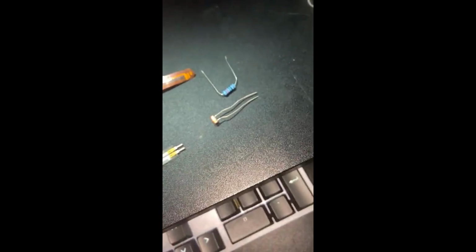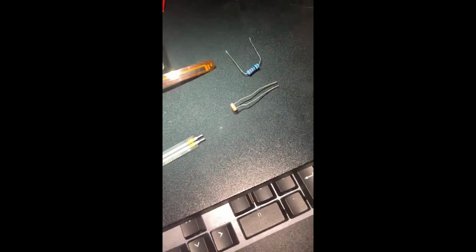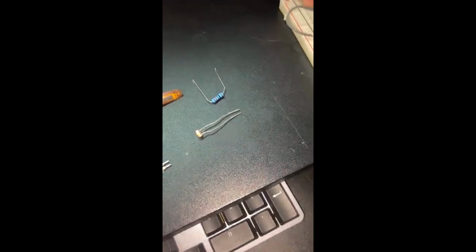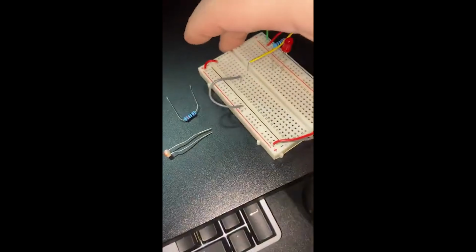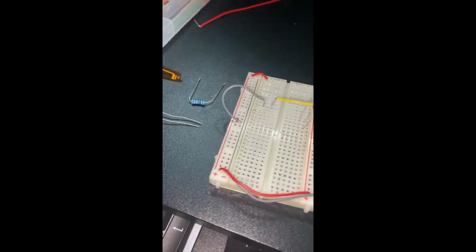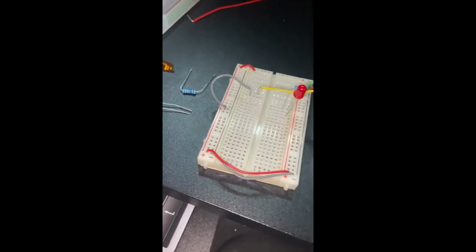So I am going to get another resistor right here. This is a 10K ohm resistor, the same one actually we used in the previous video with the button. And I'm going to set up this voltage divider. Because again, this doesn't have that built-in resistor of the potentiometer, so we have to adjust it. So I'm going to start over here, and we're going to have the same end result, but with different sensors. So I'm going to go with the force-sensitive resistor to start with. It's like a Jedi.